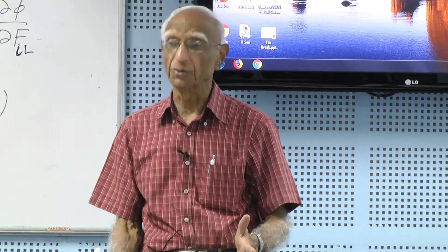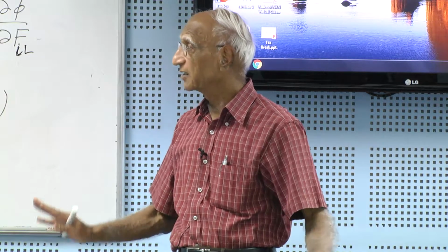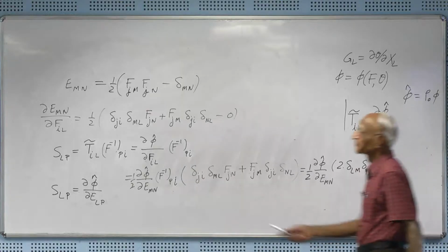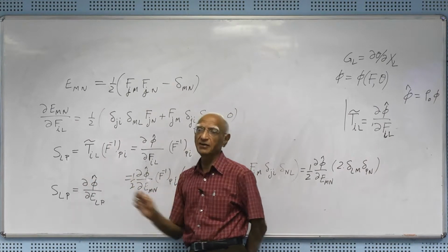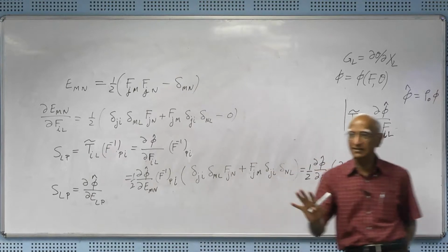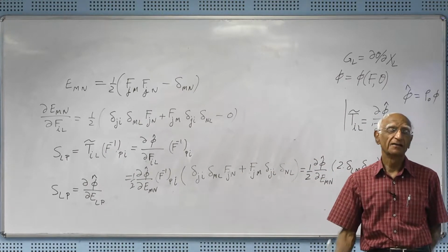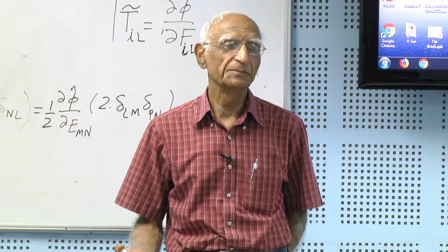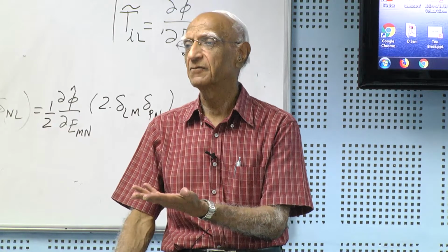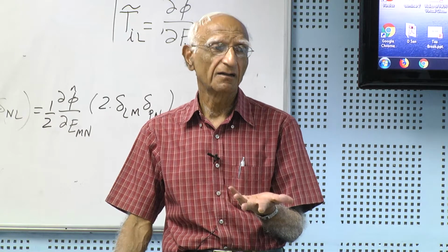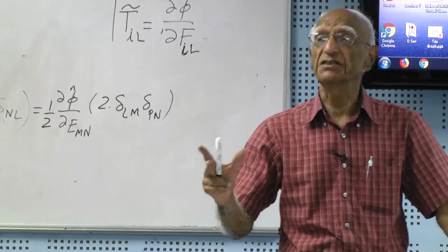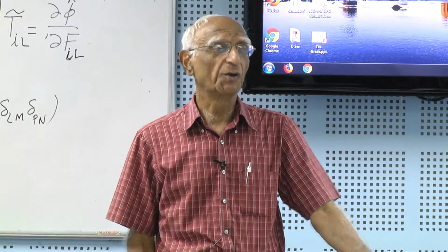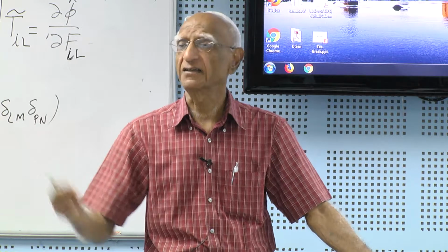It has units of stress, yes, that is true. Units of stress, yes, it has, because the deformation gradient has no units. So units of T tilde and units of S are the same. Just because units are the same does not mean it has physical meaning. Just because something is in megapascals does not mean it means something for the material. Many of us get the false impression, hey, it has units of stress, so why is Ramesh saying it has no meaning?